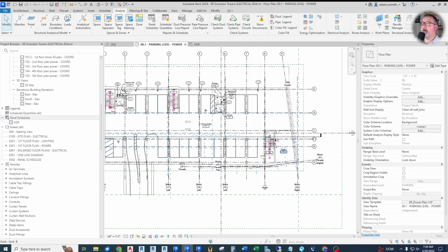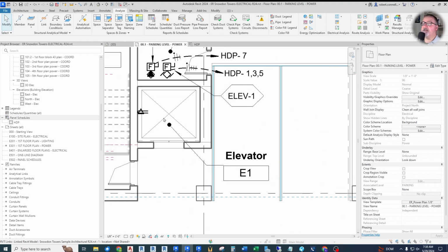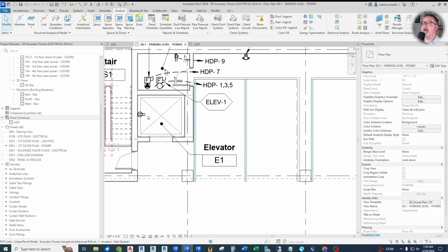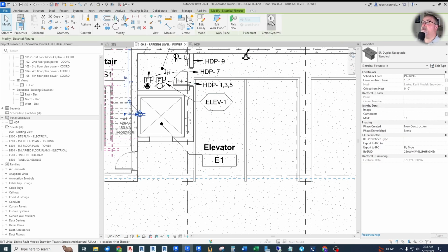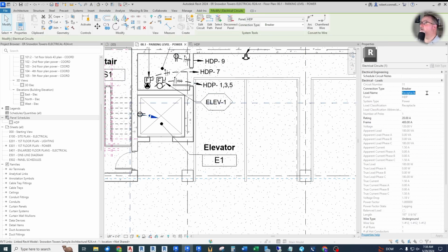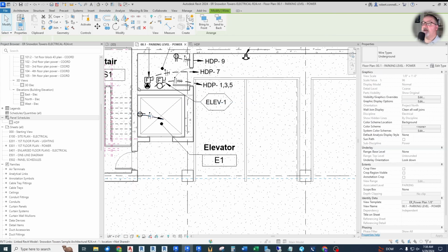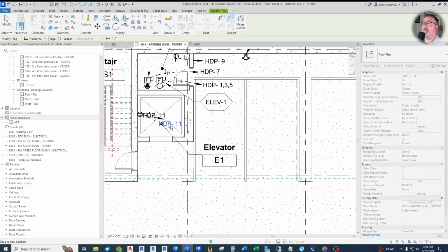Save it, of course. I realize we also did not get this elevator connected here. This guy and the machine room and the hoist, the elevator folks want those on separate circuits. So we're going to get this also powered up as we did before. Receptacle, elevator 1, hoist. And we can get a tag on this home run as well.